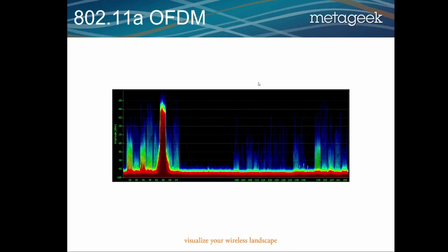Now 802.11a also makes that flat top shape. However, 802.11a is only in the 5 gigahertz band. So you'll notice that flat top shape here, with its little shoulders, and you'll see it all over. Okay. Now, in the 5 gigahertz, we can use a spectrum analyzer to know what is the best channel and